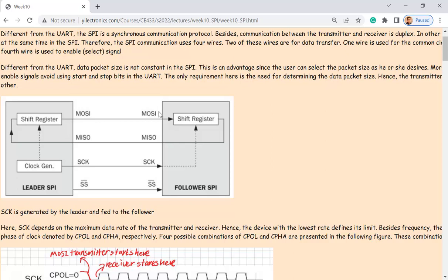So how many modules, how many different Verilog scripts do you need for these two? 4, right? So output or transmitter for master, transmitter for slave. So where is the transmitter for slave? You want to program in SO, right? Slave out. So that's a transmitter for slave. You need a digital module here.